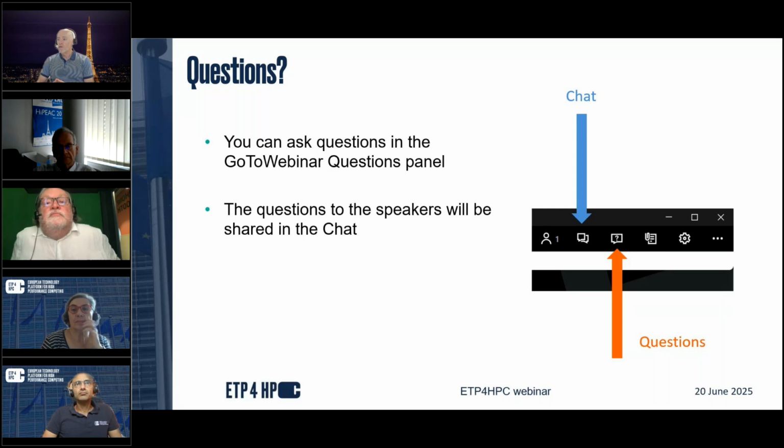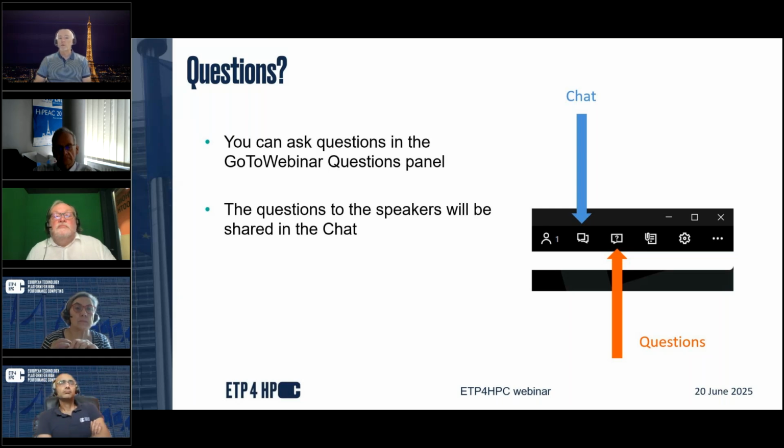But although the latency is high for CXL memory, the capacity that you can get and share is quite interesting. So this plays a part in terms of interconnect and sharing memory across nodes. So I would say we're seeing a lot of change in the different types of memory available. LPDDR now, you're seeing CAMs come on the market. Those are principally for PCs, but people are looking at those now for even server compute.